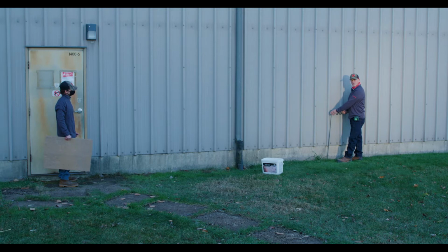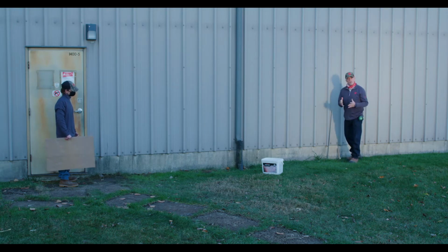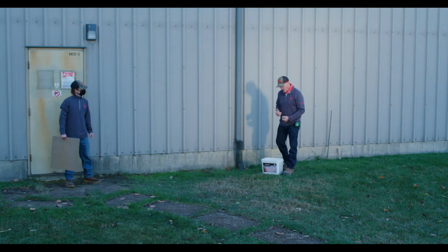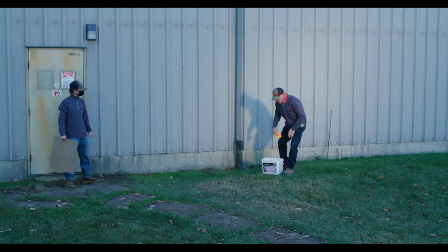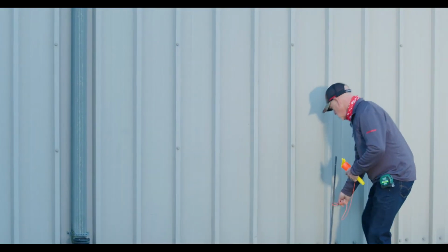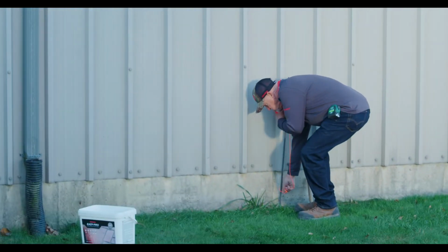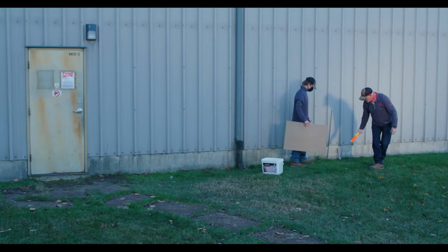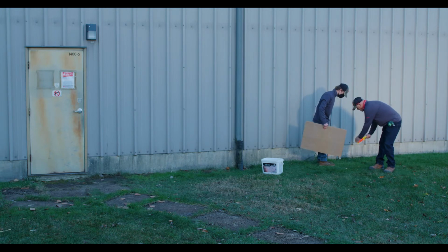All right, I've driven in this stake just far enough that if we apply slight tension to it, it won't move. It's not like a grade line where we really need high tension. For a layout line, it can be just penetrated in just enough to achieve some soft tension. Jim, if you will, you're going to take this line. I'm going to take it.